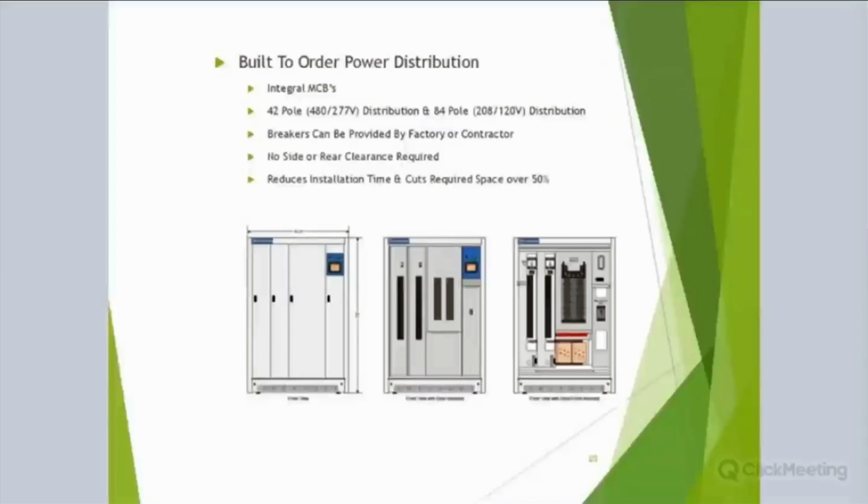Another big advantage with that is you can also build what I call an energy station, such that I need to add load or add distribution in a specific area. And I need both 480, 277, 480 volt power in that area, as well as 120, 208, or any other voltage in the secondary.